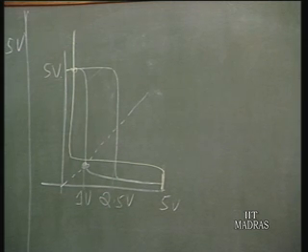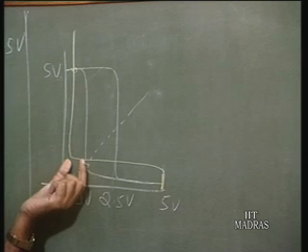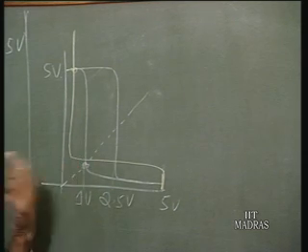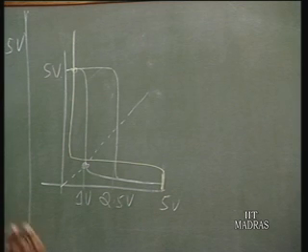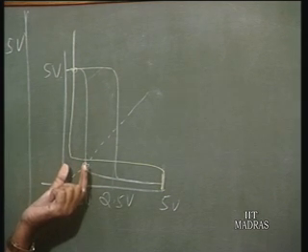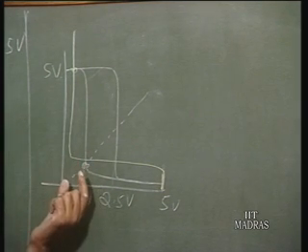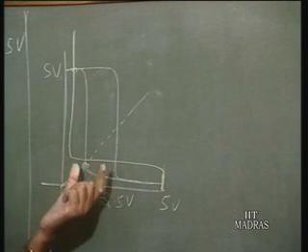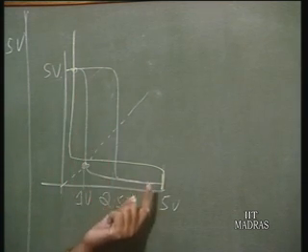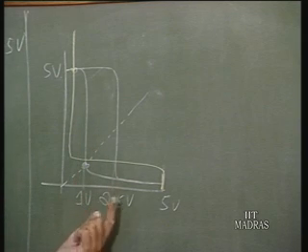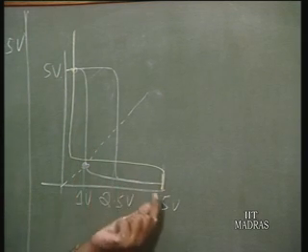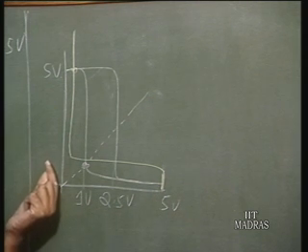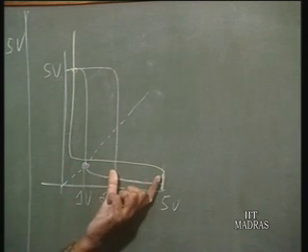There is no point having a very high value of noise margin high and a very low value of noise margin low, because in a circuit you will always have some gates operating the output at logic low and some at logic high. So if you have a low value of noise margin low, a small noise is going to upset the operation. So it is always preferred, the ideal inverter characteristic would have the logic threshold somewhere midway between logic high and logic low.